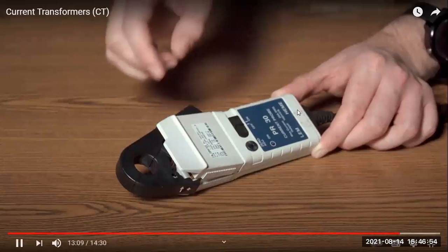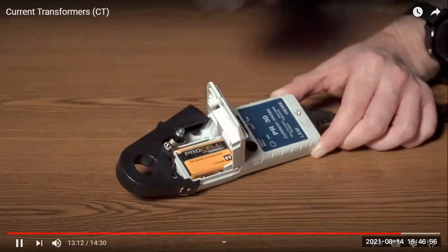A disadvantage of Hall effect sensors is that they require a DC voltage source in the form of a battery or fixed power supply. Drift can also be a potential problem, requiring them to be compensated periodically through a degaussing or calibration process. Many multimeters utilize a combination of CTs and Hall effect sensors in order to get an accurate current measurement.